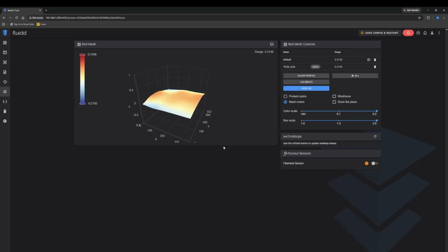This affects mostly the first layer, but if your first layer is bad, everything on top of it can be messed up also. When you install K2 Improvements No-Cartographer option, the printer is saving meshes by bed temperature and chamber temperature. So 70°C bed temperature, with 0°C chamber temperature. It will make a new combination bed mesh every time you change temperatures.